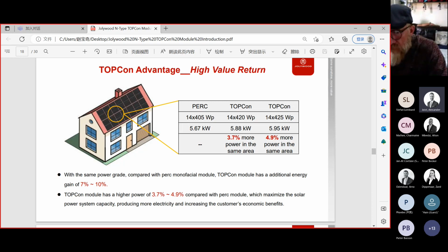Normally all inverters now, it was different a while back when they only had 12 amp, but the inverter manufacturers changed in the last year, and they can actually take up to 15 amp on an MPPT input. So that should be no problem in my opinion. And if it's an issue with your inverter, bring it up with the inverter manufacturer.